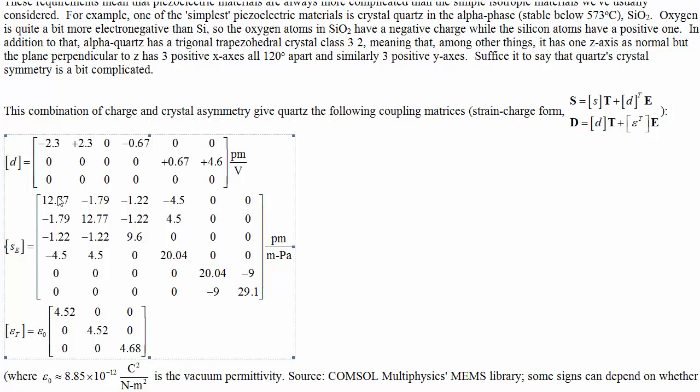We have seen the compliance tensor. This is old news for us at this point. And we haven't bothered with the permittivity, but there's nothing too scary about its permittivity matrix. Quartz isn't asymmetric enough to map electric fields in X to charge displacements in Y or anything like that, unless we're also applying appropriate boundary conditions and exploiting its piezoelectricity.